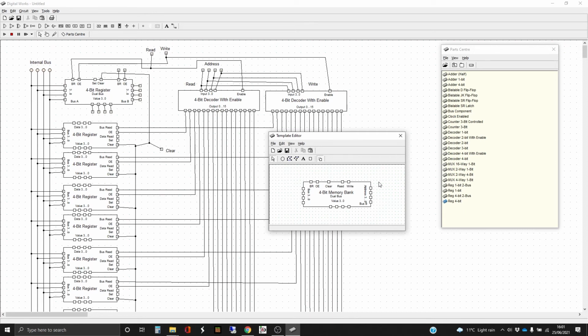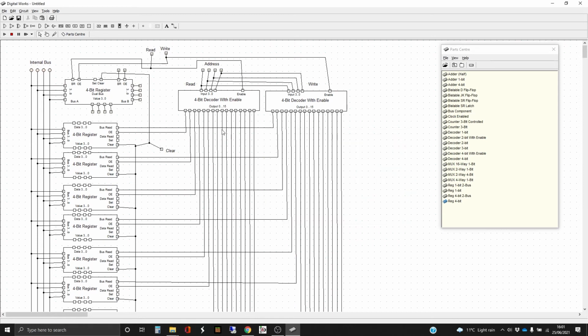Kind of just checking my head again. So we've got 4 pins there for the bus, 4 pins there for the bus, output enable, and bus read. That's fine. We've got 3 commands: read, write, and clear. So we've got an address input, which is going to be here, and we've got a value output over here. So I'm going to go back to, yet again, the music as I fast forward, as I wire that up. Okay, here we go.